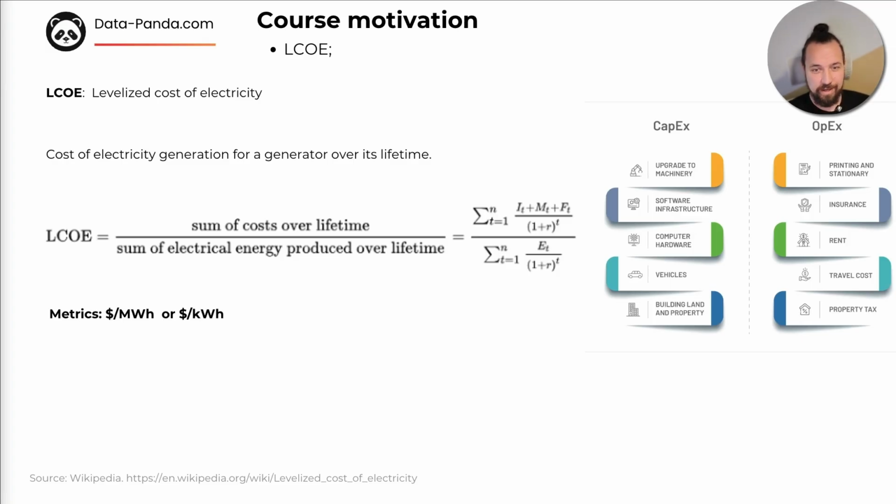So none of this is correct. That's where LCOE solves this problem by asking, over the lifetime of each system, after accounting for all costs, capacity factor, fuel, and utilization, how much will each megawatt hour or kilowatt hour of electricity actually cost to produce? That's why LCOE is so widely used.